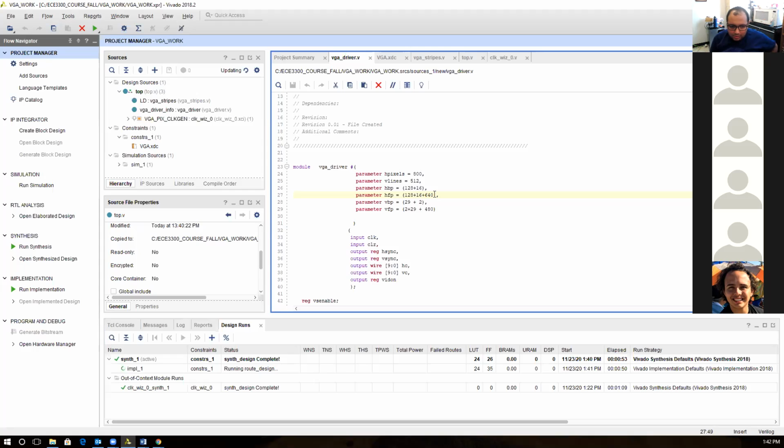Super. I see the implementation actually got increased a little bit, and there is an explanation for that. The explanation comes from the routing inside the floor plan. Maybe the tool decided that for the shortest paths it would be better to increase the number of registers, the flip-flop sequential circuit elements, so it will be better in terms of meeting the timing of the maximum frequency of 100 megahertz and the pixel frequency of 25.1 megahertz.